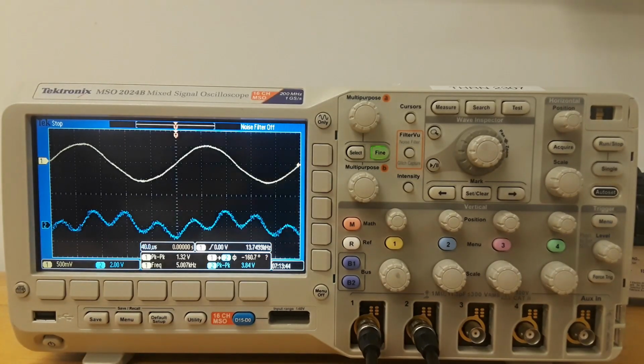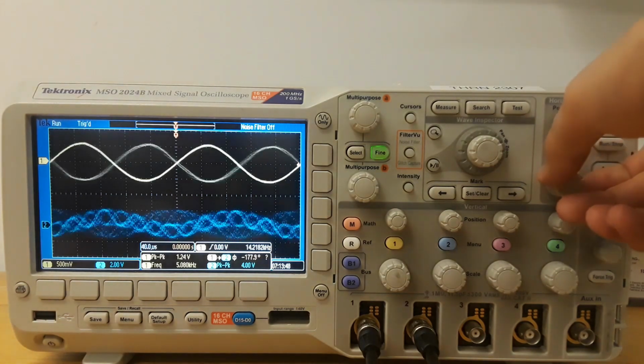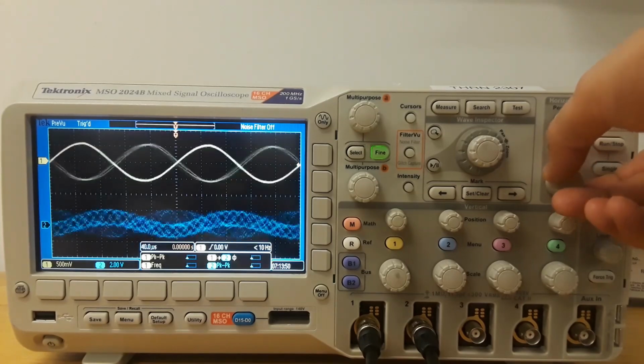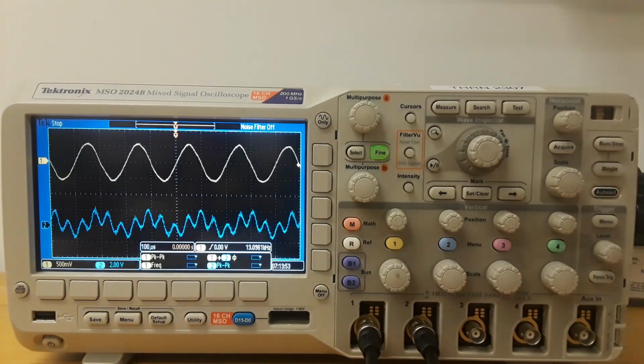The output waveform is going back to 0 a lot of the time. And you think about what we told the processor to do, that's exactly what we'd expect. We're telling it every second sample to go to 0. In this case, we could actually physically see that going to 0 each time. You can still see the 5 kilohertz signal in there, but it's got a great deal of high frequency noise as well.